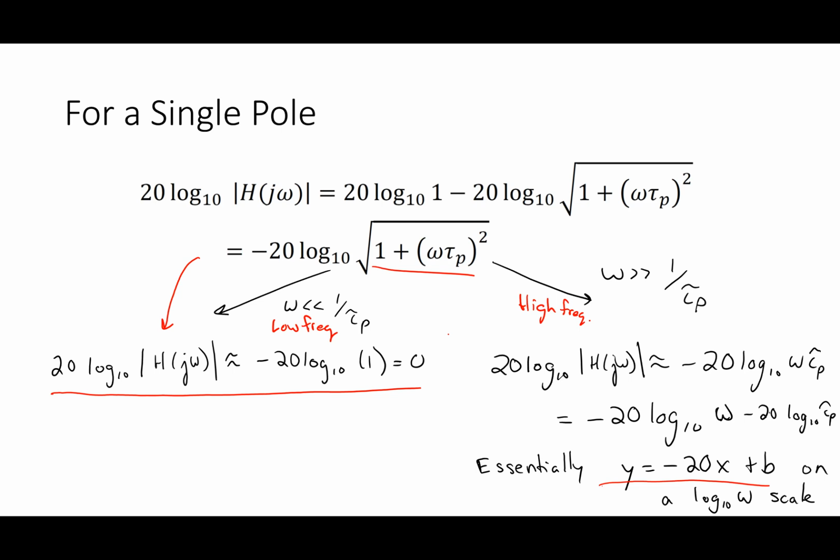So basically what I do is I take 20 log of that magnitude, so that becomes this whole thing. And I said, all right, I break this up into two frequency ranges. I made an argument. I said for low frequencies, this guy is flat. So as frequency increases, the magnitude that I drew for this would be basically sitting at 0.